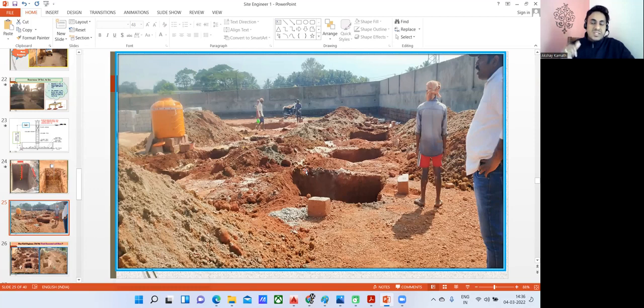You have to contact the structural engineer, saying that we are getting soft soil there, and in that case we can try to excavate another 1 or 2 feet, so that we are going to get the hard soil strata. Most of the time we get it. Okay, otherwise you can do the soil investigation, and you can come to the conclusion.